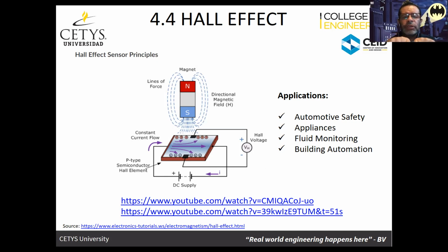field. So the Hall effect, quick summary: if we have any sort of thin film that's a conductor and we apply a current through that conducting film, the electrons, the carriers, are going to align themselves. And we immerse it in a magnetic field. The particles are going to align, and there's going to be a voltage that's perpendicular to the movement of the current, and that's called the Hall voltage.